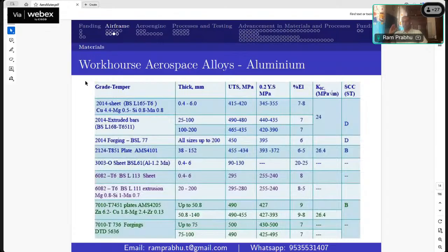Okay. When I need a strength and toughness combination, I go for aluminum copper. When my focus is only the strength, I'll go for aluminum zinc. And when I need a very good formability, aluminum magnesium silicon. That's all the logic to understand. These numbers, you must have a sense. You cannot have an aluminum alloy which has a strength more than 550 MPa.